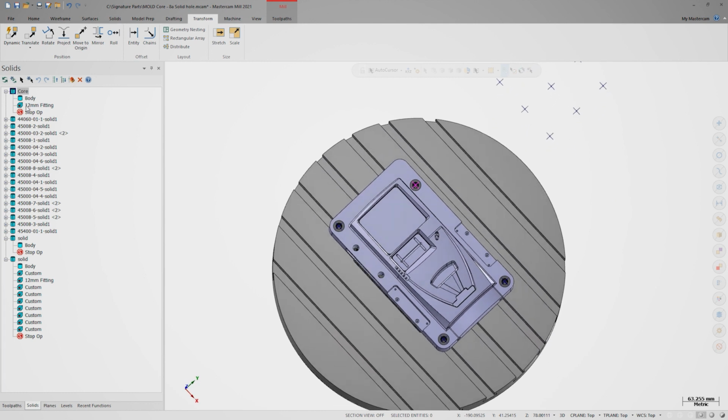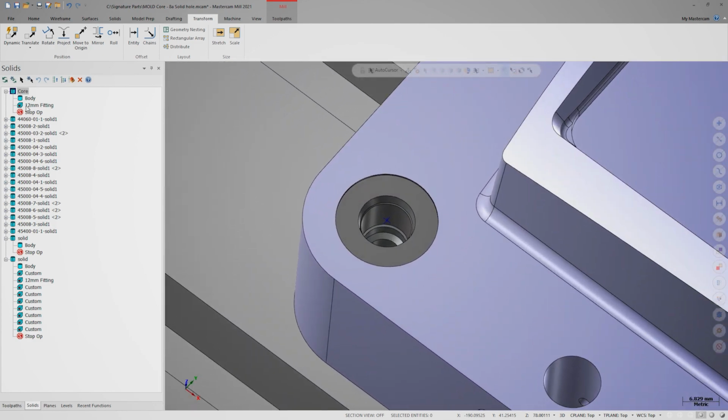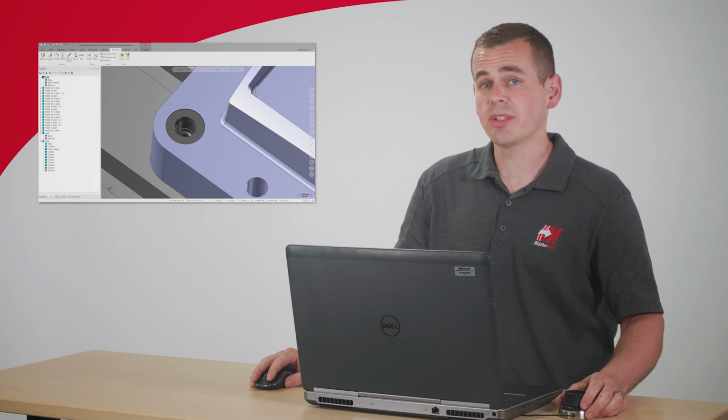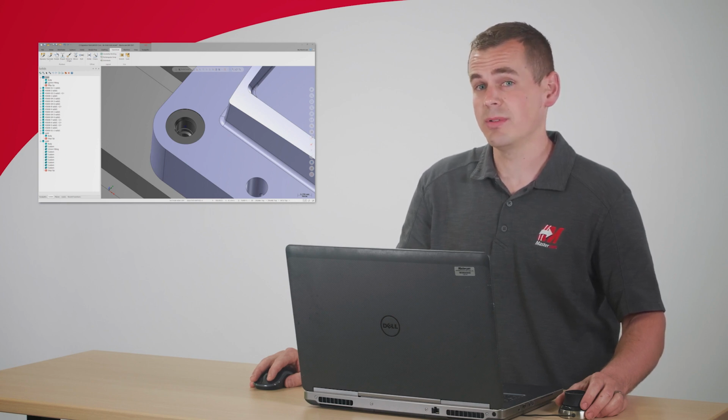Another helpful feature is that the solid hole's color is saved in the template when it's created. If you need to machine several custom hole types on a regular basis, this functionality lets you color code your hole templates. This means that when it's time to program your toolpaths, it's very easy to identify the different hole types, and you can even leverage functions like Mask on Color for easy drive geometry selection.